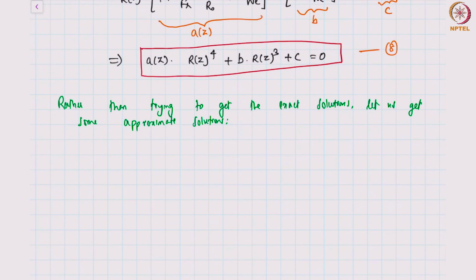So let's consider the Weber number very large limit, which means that inertia is much larger than surface tension, and therefore you should expect that in that limit surface tension will cease to be important, and now you have a balance of only pressure, inertia and gravity. So gravity is the driving force which is pulling it down, and that causes an acceleration and generates inertia in the system.